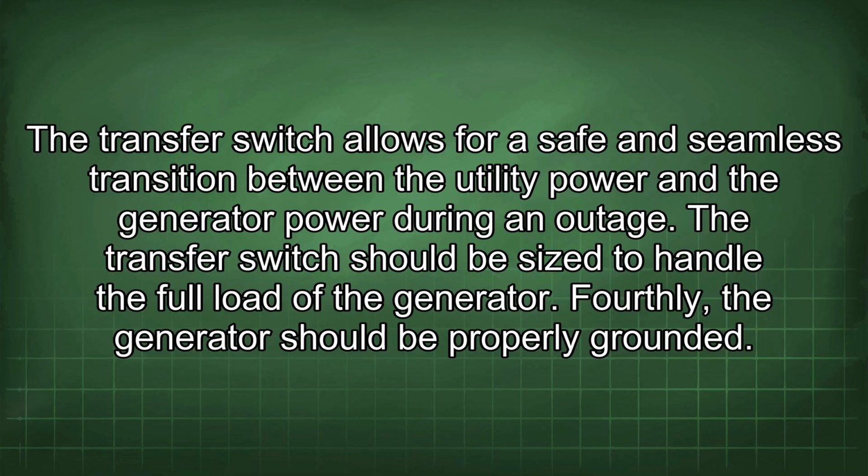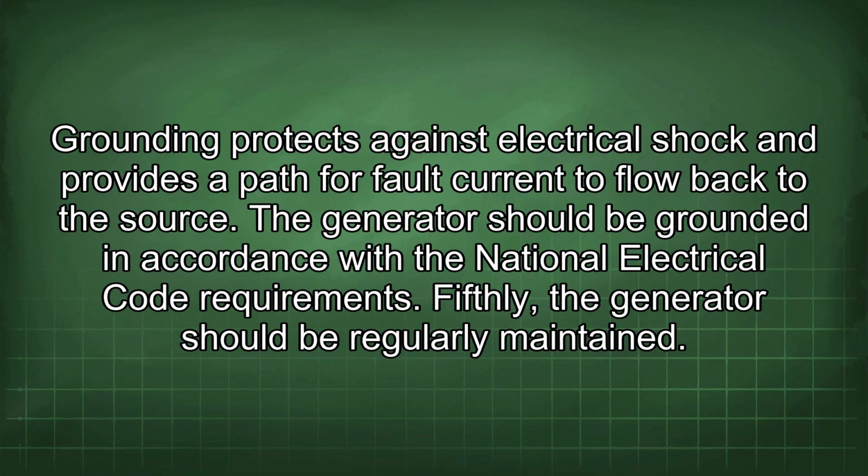Fourthly, the generator should be properly grounded. Grounding protects against electrical shock and provides a path for fault current to flow back to the source. The generator should be grounded in accordance with the National Electrical Code requirements.